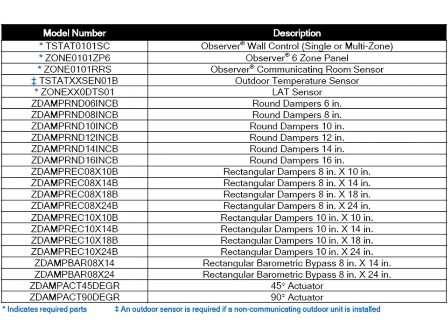The one thing you can't do is, on the same zone damper output, you can't mix different types. You can't have a spring-loaded one and a power open, power closed on the same output. But zone 1 could have a certain type, and then zone 2 could have a totally different type. That's fine.